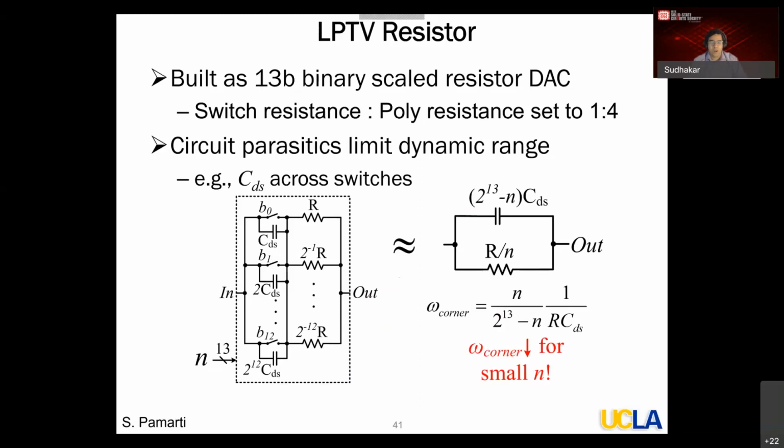When you're switching these things at a fairly high speed, the capacitors can limit how fast a DAC you can effectively realize, so you have to be a little careful. But again, with technology, this trade-off is in our favor. With technology, the R-C corner is only going to move higher and higher to help us.